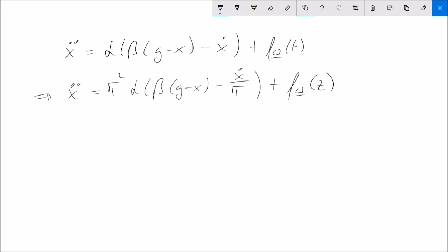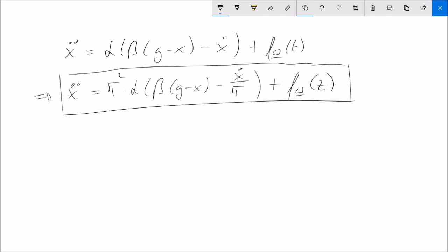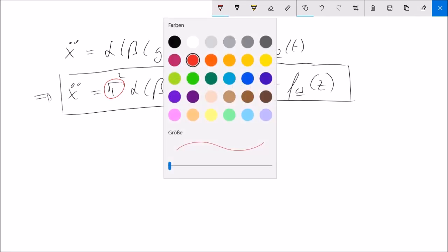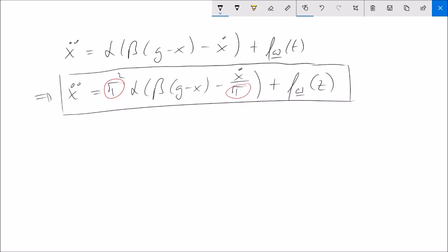So this is now our normalized trajectory generator, and now you're maybe asking what these taus are which I have introduced here. And these taus are a so-called temporal scaling. Just imagine you have now normalized your desired trajectory from 0 to 1.